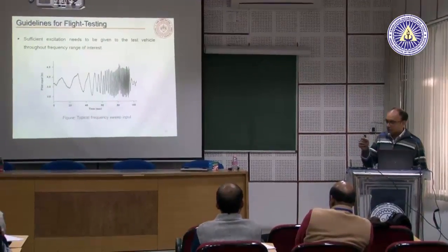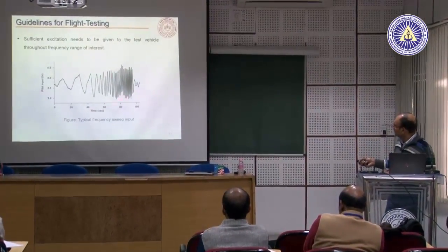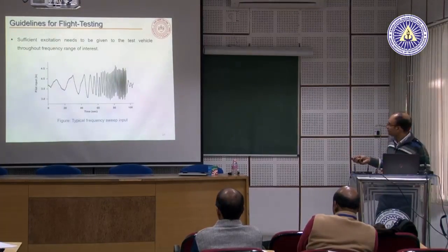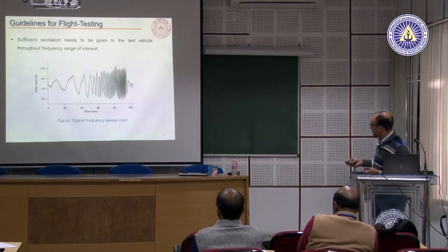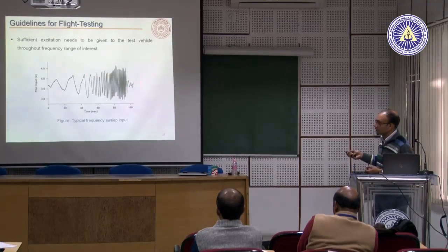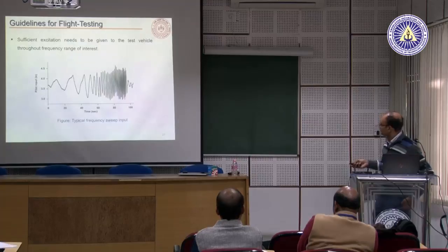That is why the pilot starts with a low frequency. He will start moving the stick slowly, and then at some point he is giving very high input. This is just the pilot input, which is recorded. This is a typical frequency sweep input, and you can see that the frequency is increased continuously, and then probably it will be decreased again.